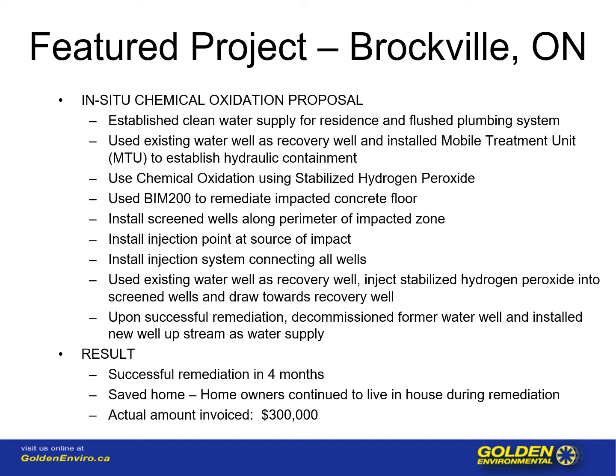We used chemical oxidation. In this case, we used stabilized hydrogen peroxide. And the reason that we used hydrogen peroxide on this particular job is because of its quick reaction. Moving through bedrock, you want your oxidant to react quickly when it comes in contact with the contaminant. If you use an oxidant similar to the one we used on the pigeon job, it would take too long to react with the contaminant. Hydraulic conductivity through this particular bedrock was very fast, so we needed a quick reacting amendment.